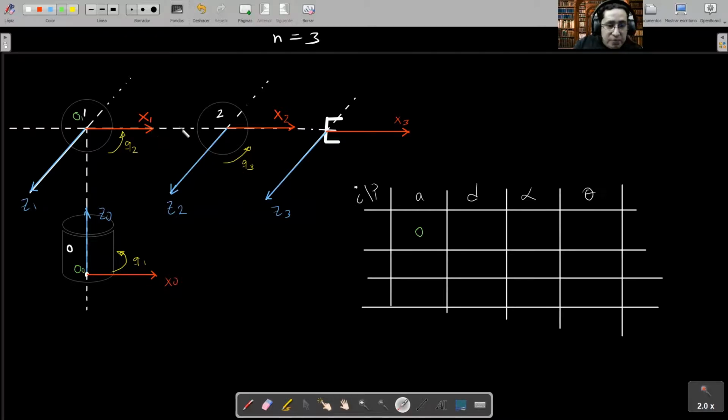I mean, again, the intersection of X1 with respect to theta 0, and we find the point and we measure the distance with respect to the current origin, which is the same point, then the distance is 0. The distance directed along X1. Okay, next, we are to find the distance along the C axis, distance from this and this. But the algorithm says is the intersection again from X1 to theta 1, which is again this point, the origin of the